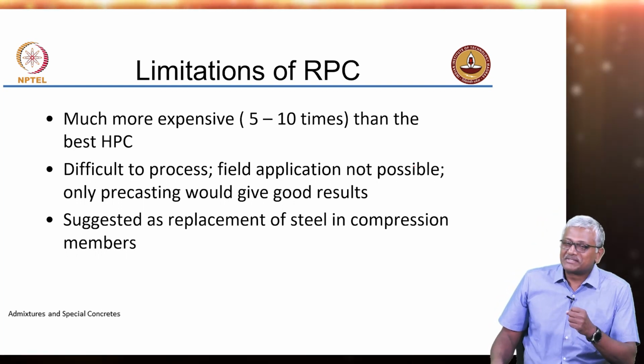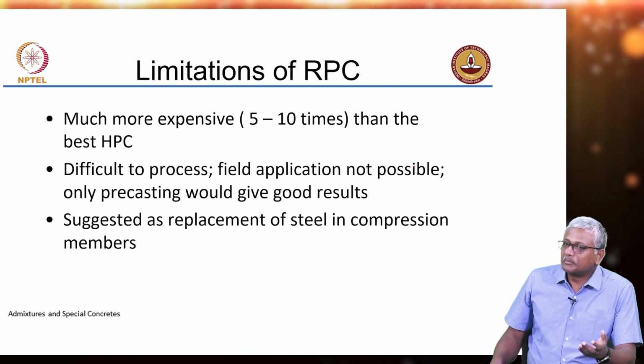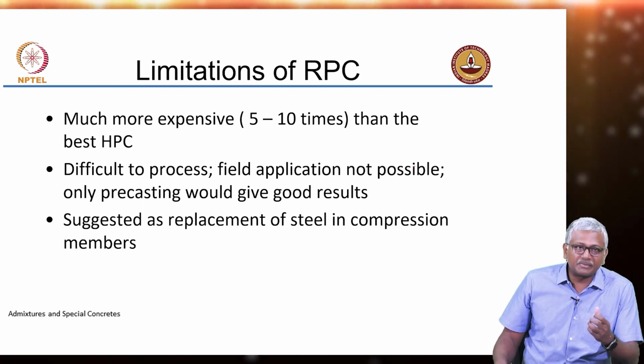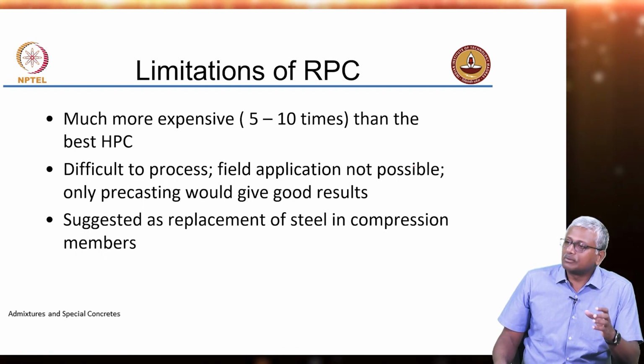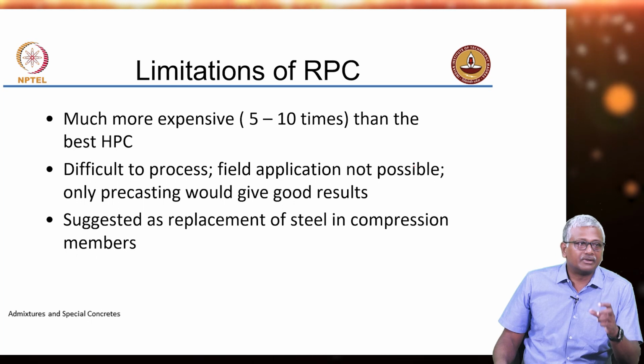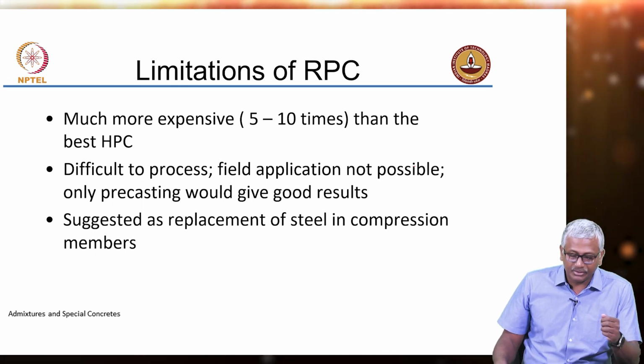So that is why such concretes are possible mainly in precast factories where you have some control and where you do not really need long workability retention. So precasting would be a good solution for use of relatively high, ultra high strength concrete.